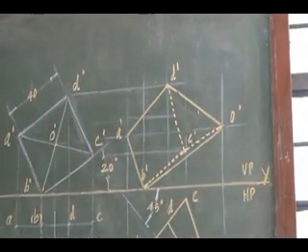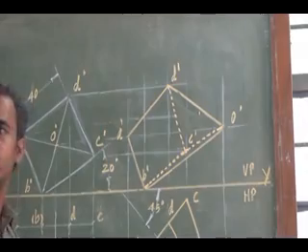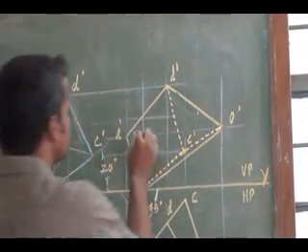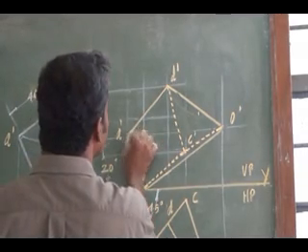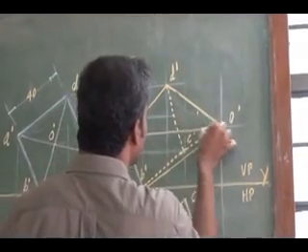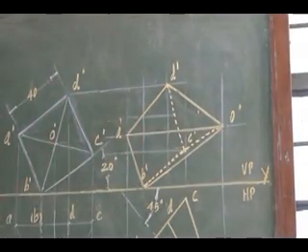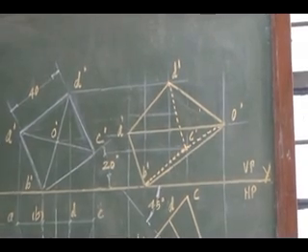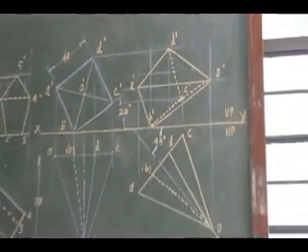But A2O will be a visible one. This is visible from the bottom. AO is a fully visible slant edge. So this is how your final front view looks. Clearly, carefully show the visible and hidden details.